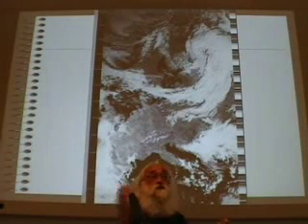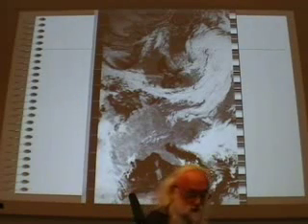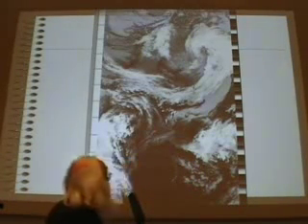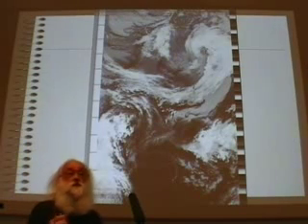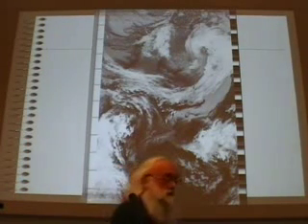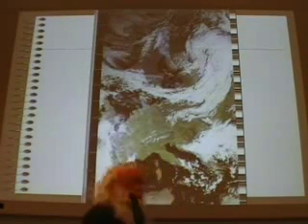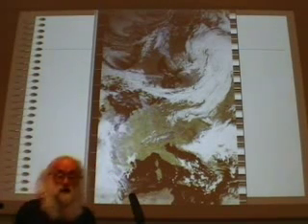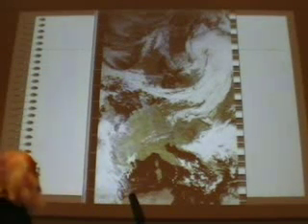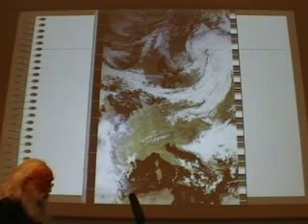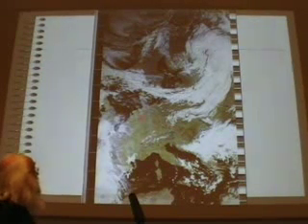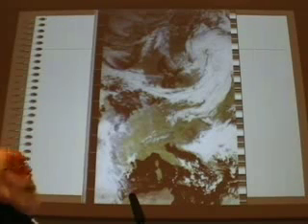So, visible channel, you can tart that up a little bit with histogram correction, a bit of stretching, whatever, to make that look pretty. The thermal channel, you can perhaps use that to provide colouring information in an image. And then combining those two together in standard TV techniques of colour and brightness, you can produce this false colour image that has a reasonably attractive appearance.